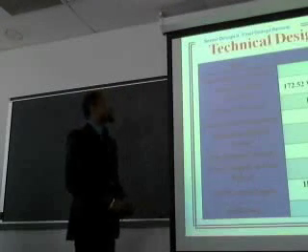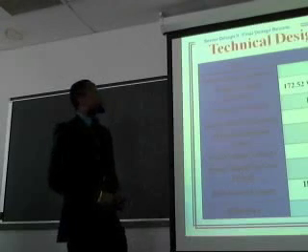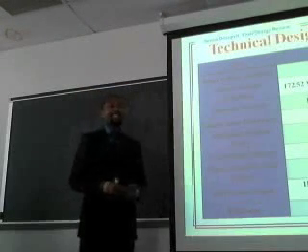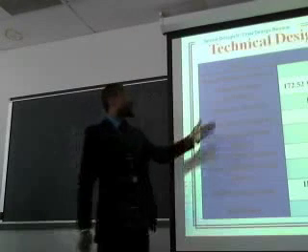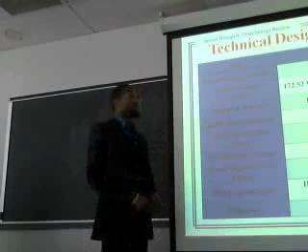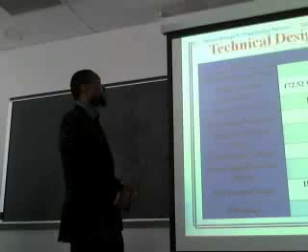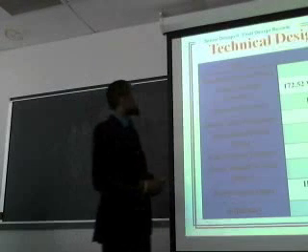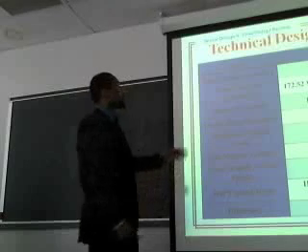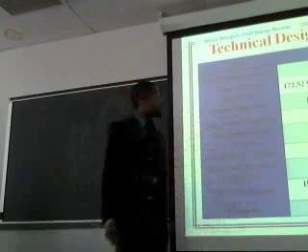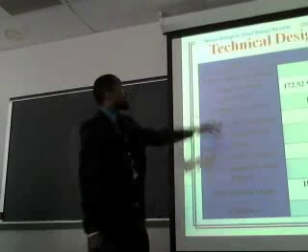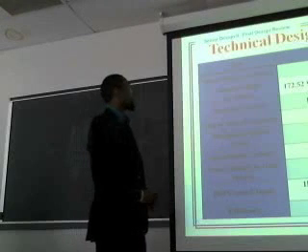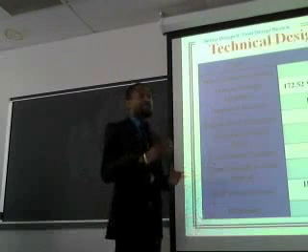And here we go. This is our technical constraints. This is all we have to deal with throughout the whole project. And thankfully, thank God, we accomplished all our technical constraints. Here we have our input voltage between 110 to 120 volts, and the output voltage of the rectifier, which we use right here, is 172.5 volts for the rectifier that's converting the AC to DC.